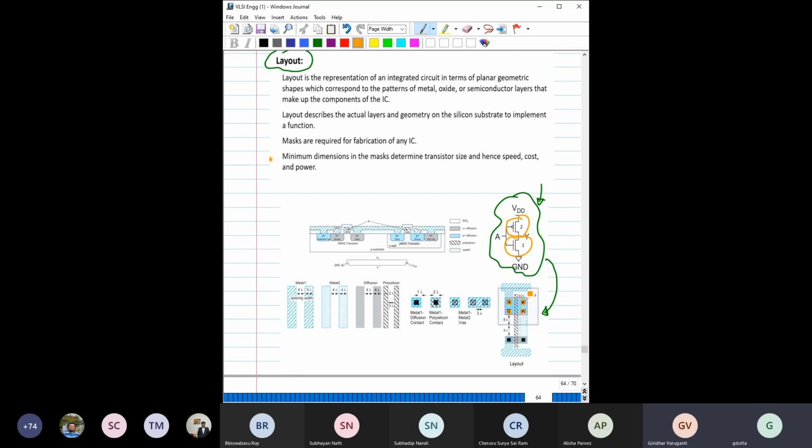Okay, and these are the terminals, these two terminals, drain terminal and source. So this is the drain terminal for this PMOS, and this is the drain terminal for NMOS. So you can see, compared to NMOS, the PMOS width, width is basically this one. This is NMOS width and this is PMOS width. Okay, and this is the gate, this part is the drain, this part is the source. So this part has been taken as a source contact, this part has been taken as a drain contact.